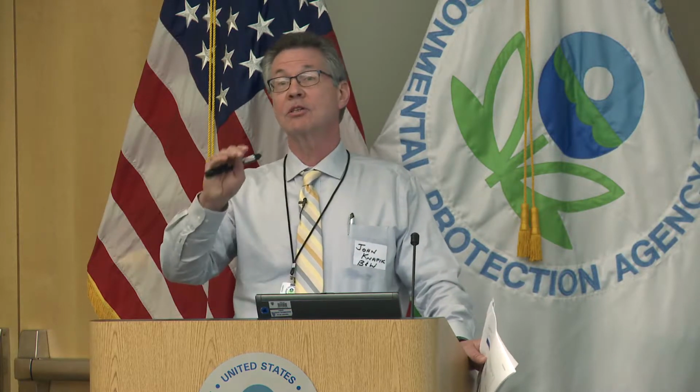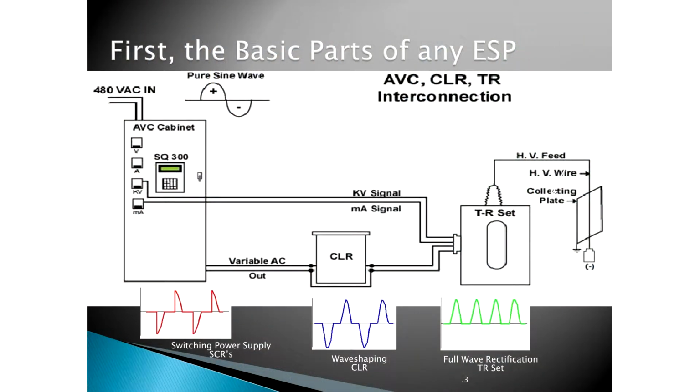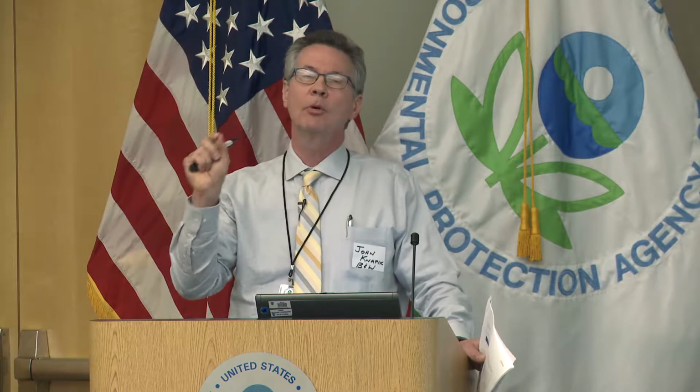So it sees and it says, my job is to constantly push to increase the power to the maximum to that transformer if possible. Well, if that's the case, why don't I just take the 480 volts in the power plant and send that directly to the transformer and let it be? It's because in precipitators, all precipitators, or most precipitators, have sparking going on in the precipitator. Sparking between the high voltage electrode and ground.